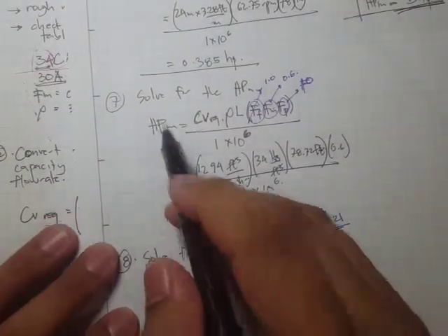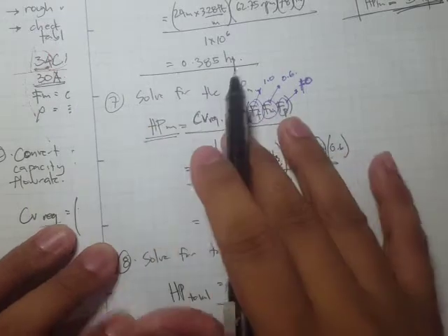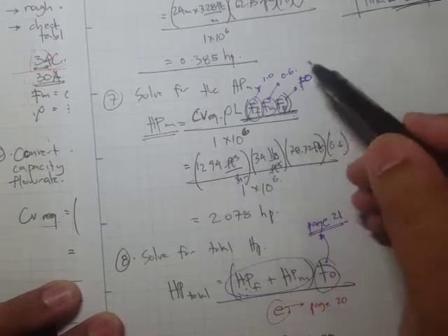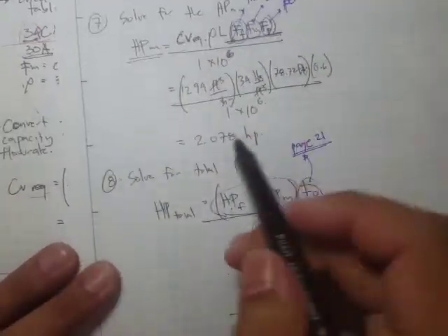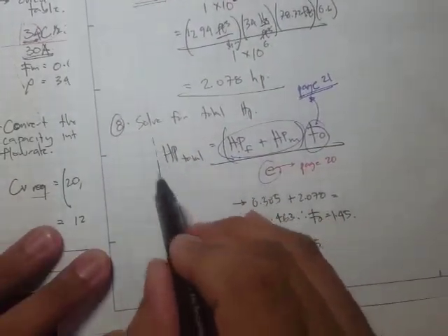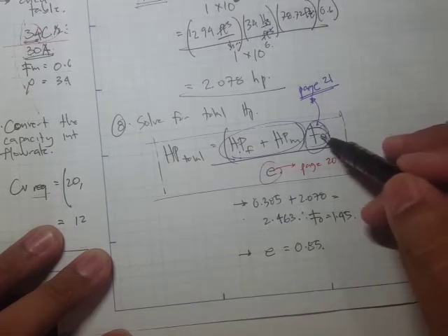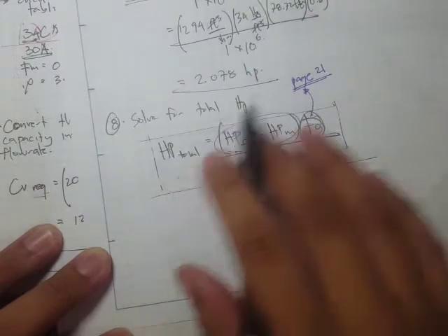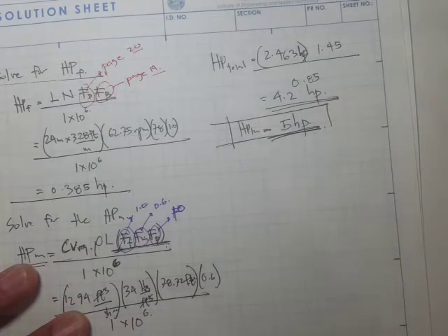Okay, so the next step that we did is to solve for the material horsepower, and we substitute again. There's a given equation, and we just substitute the values for these factors right here. We just substituted the values from the table. Okay, and then you have this. And finally, for our total horsepower, we obtain this overload factor, then divided by this drive efficiency, and then we solve that we need a 5 horsepower electric motor.